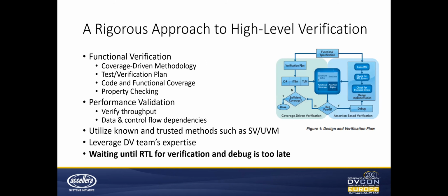So how do we achieve this? Well, much of what I'm describing here should be very familiar to most of you. We're doing most of what you're accustomed to, but with a focus on the pre-HLS design source instead of the RTL. We can leverage familiar coverage-driven and verification plan-driven methodologies that use both code and functional coverage to track progress.